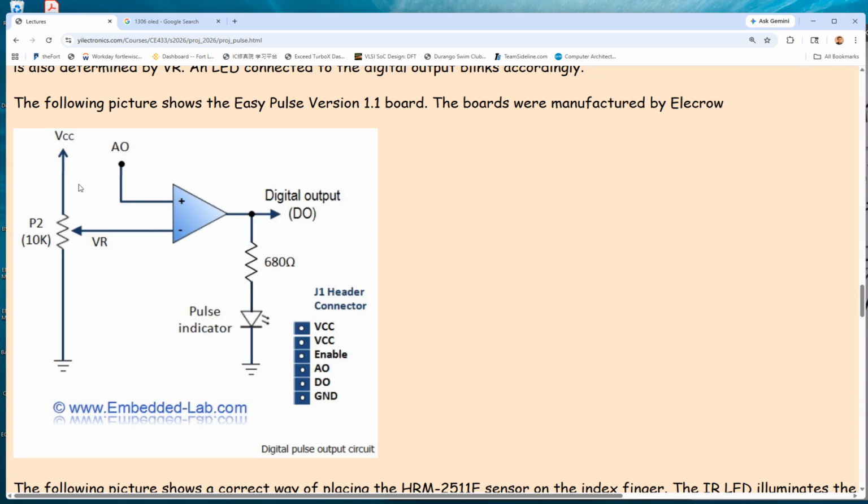Yeah, the analog signal here, you can control it to swing from 0 to 1, but does that matter? I think we should, because it's for next year's, right? So we should always keep it within 0 to 1. But for here, because this guy is powered up by 1.8, which is the minimum voltage power supply, the digital signal will be 0 to 1.8, and then you have to divide it further. Okay, so make sure that you show an analog signal output with a 0 to 1 swing, and also a digital signal with a 0 to 1 swing as well. Okay.